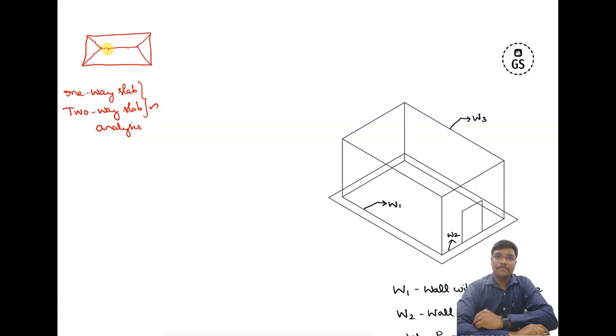So when the loads are distributed like this, what happens from the slab? The loads are distributed to beams. So from the slab, the loads are distributed to beams now. So I'm going to take this beam. The loads are distributed in kilonewton per meter square. And when you talk about this particular beam, now it applies as a UDL. So kilonewton per meter square is multiplied with meters, say for example, this is the span length.